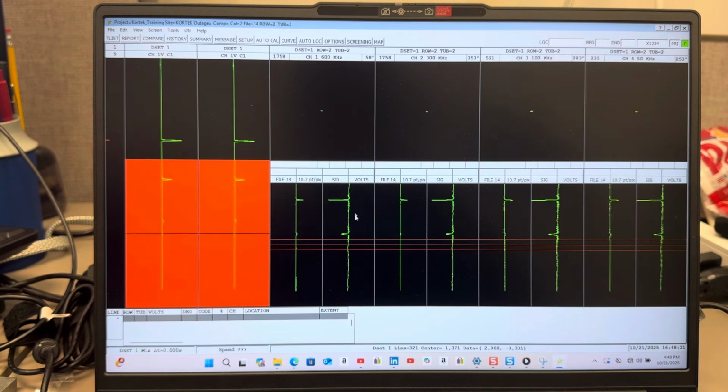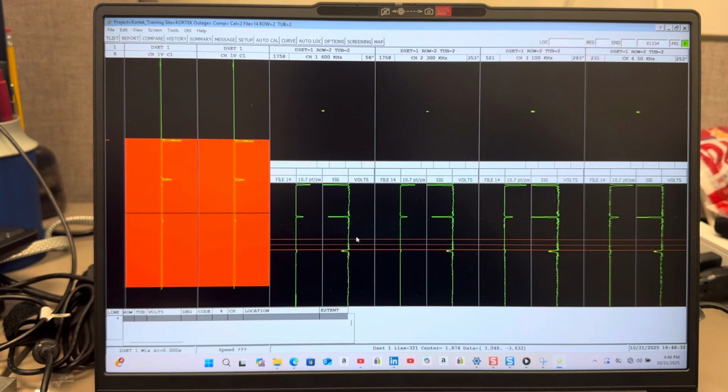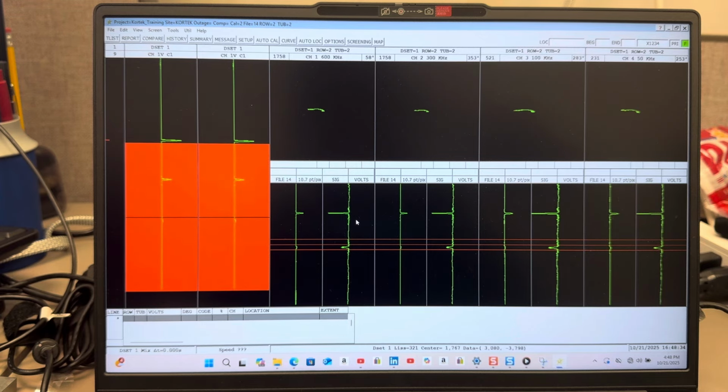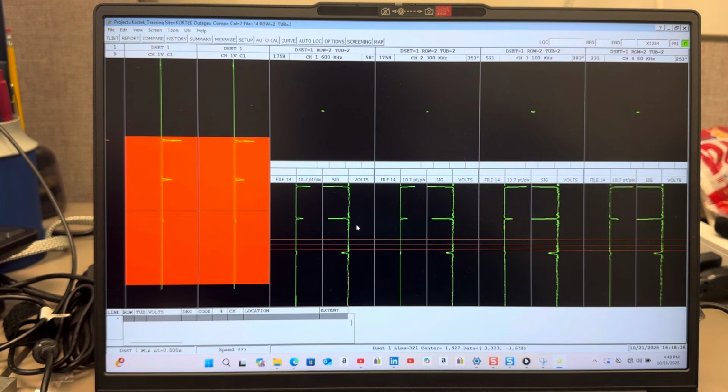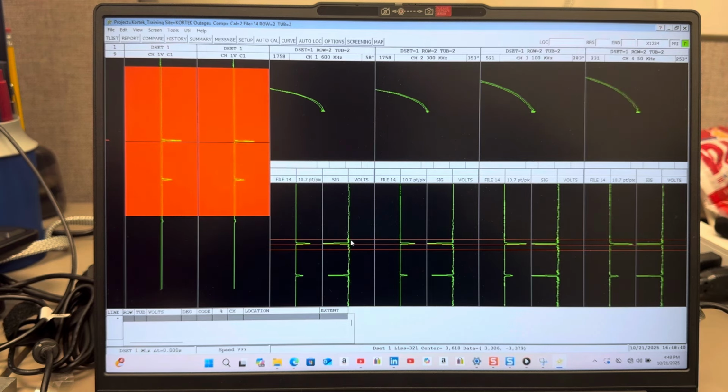In other words, I'm going to hold down my index finger button, click and drag, and pull the data down into the window. That's the scanning direction. So there's my 8 mil deep surface breaking notch, there's my 20 mil deep, and there's my 40 mil deep.